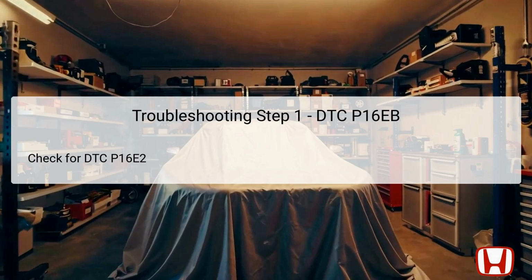The first step in troubleshooting DTC P16EB involves confirming whether DTC P16E2 is present. This serves as a preliminary check that can help pinpoint additional related issues. To begin, access the vehicle's diagnostic tool and check for codes. If DTC P16E2 is indicated, it suggests that there may be overlapping errors that require attention. If P16E2 is not present, it points directly to issues strictly related to the active exhaust components and communication. A clear understanding at this point allows for a more targeted approach in subsequent diagnostic steps.